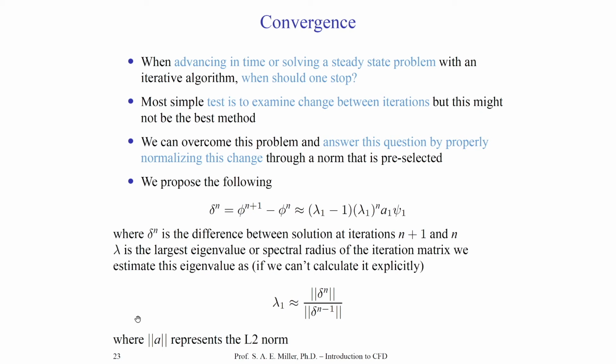Now, this is very theoretical, and in practice, what you can take away in a CFD solver that's solving a nonlinear set of equations is that over time, not locally from one iteration to the next, but maybe over thousands or tens of thousands of iterations, your residual should keep decreasing.